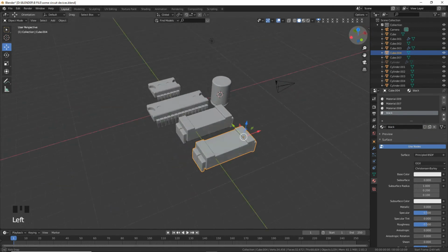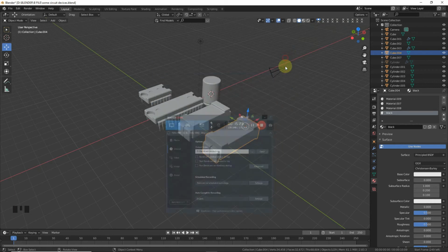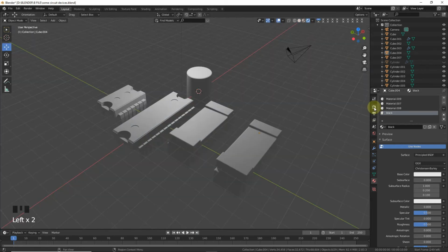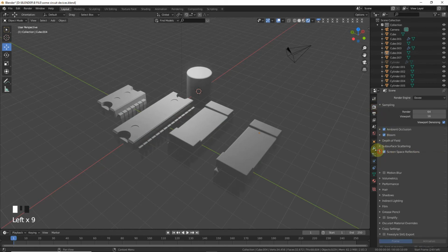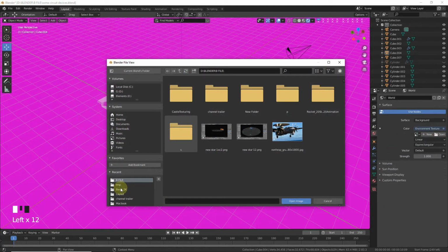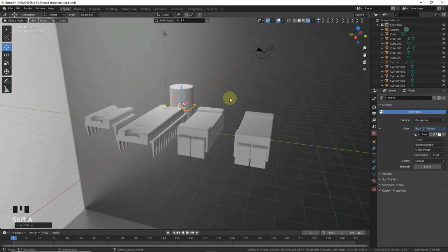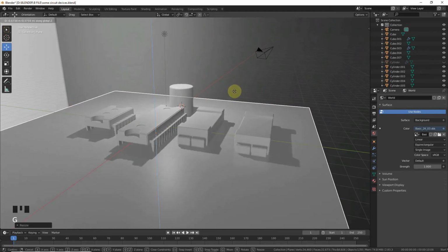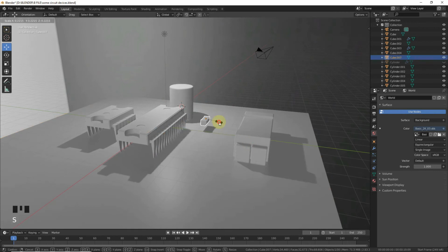Okay, now it's time for adding materials. Now go to render viewport, check ambient occlusion, screen space reflection and refraction. Change the environment texture and import environment texture basic 2K003, Shift A, add plane, Alt G, scale, grab it down around here and scale down.